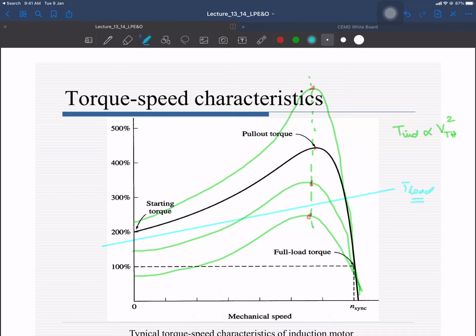So now let's suppose that I have the load torque that is like this. This is representing the load torque, and I want to operate my machine, let's suppose, at this particular speed, right? This is the requirement. So I should adjust my torque speed curves in such a way that there is a point of equilibrium at this point. Why select this point? Because this is the load torque and we require this speed. So at this speed your motor torque should be equal to the load torque. If that is the case, then your machine will be operating at this point.